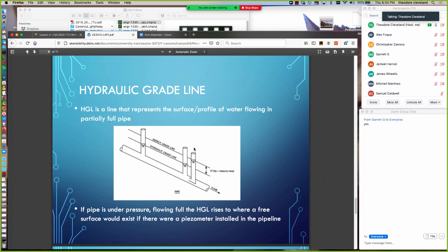And we could actually measure that if we were willing to put a pitot tube into our pipeline. And in real pipelines, that's probably almost never done. Certainly not in water distribution pipelines. We do them in fluid mechanics labs sometimes. And so this pitot tube is sampling roughly the same location that the piezometer is sampling.